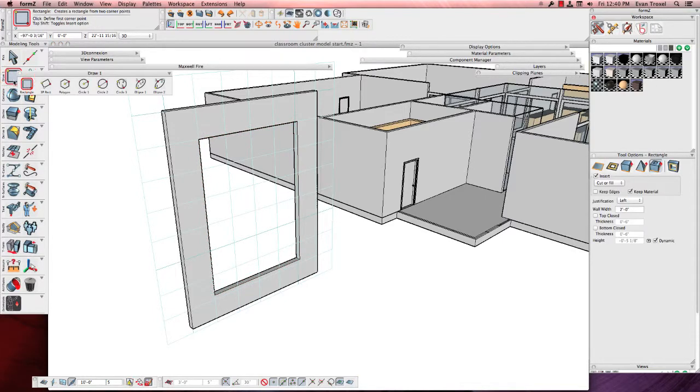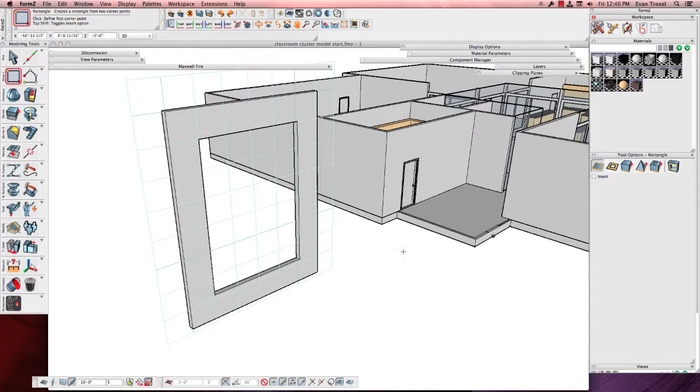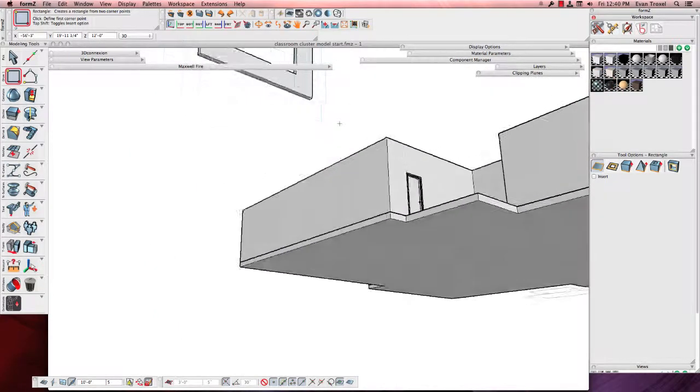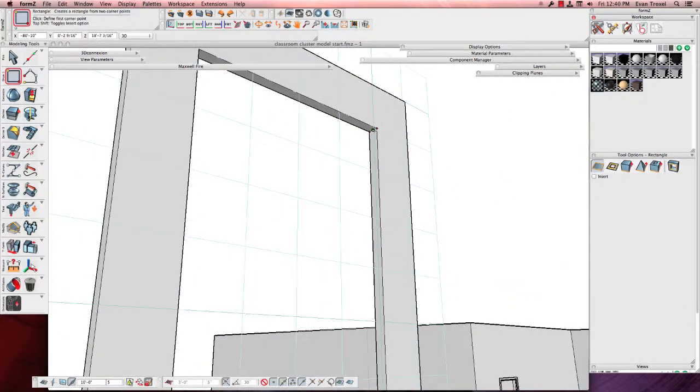What that allows me to do is now go and draw a two-dimensional surface. I'm going to turn off this insert button because I don't want it to glue to that geometry. I want this to be a separate object. I'm going to choose glass. And using my Space Explorer, I'm going to zoom in and snap to the midpoint. Because I have object snaps turned on down here, and right here is my interval snap turned on, midpoint is one of the intervals.